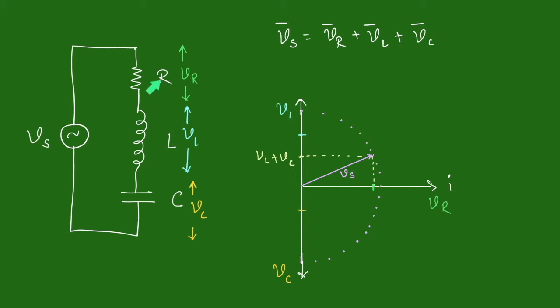When we connect a resistor, an inductor and a capacitor in series with each other and connect an AC voltage source across this series combination, using Kirchhoff's law, we should be able to write Vs equal to Vr plus Vl plus Vc. But here we have written it in vector form. Why should it be like this? It is because Vr, Vl and Vc are not in phase with each other, and so we need to write the equation in a vector form.